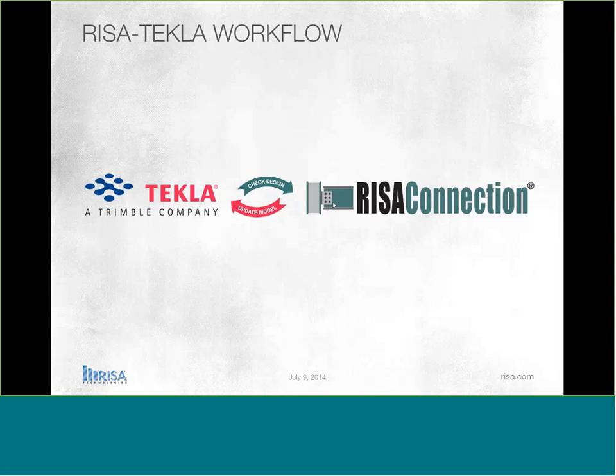What we're doing over in RISAConnection is the engineering portion of it. We're taking all of the forces that you've laid out in the connection, and you're going to check that connection against the code. So we have some American codes in there, so we have ASD or LRFD. You can do the design and pick that type of code. We've also recently added the Canadian codes, so you can design all of your connections based on the code.